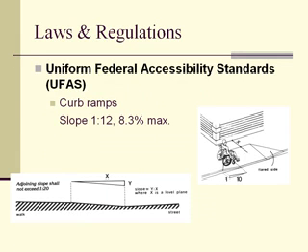So it's best to avoid designing at that 1 in 12 slope, and instead do a softer slope, something definitely less, to avoid non-compliance. And there are specific requirements for the curb ramps. The main slope is 1 in 12, but the flared sides, in occasions when there are landings on top that are at least 48 inches, are allowed to have a 10% running slope, which is a higher slope than this. But as I said, these slopes are maximums, and we should design well below these to avoid non-compliance.